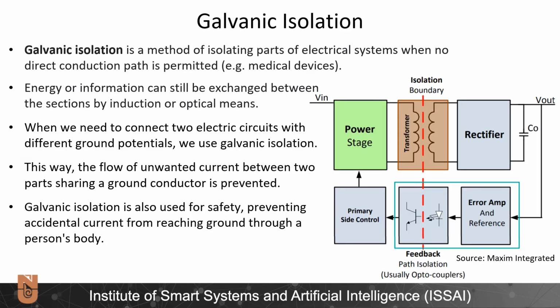In the beginning of this lecture, we told that we are using transformers mainly for power transmission. We are generating power at a power plant, and we are using step-up transformers to bring that voltage to a higher level, such that we just carry it using a low amount of current over transmission lines to long distances. And we use step-down transformers to decrease it to a lower voltage such that the customers can use it for varying purposes.